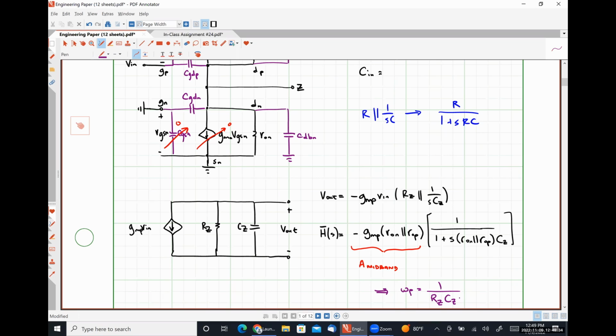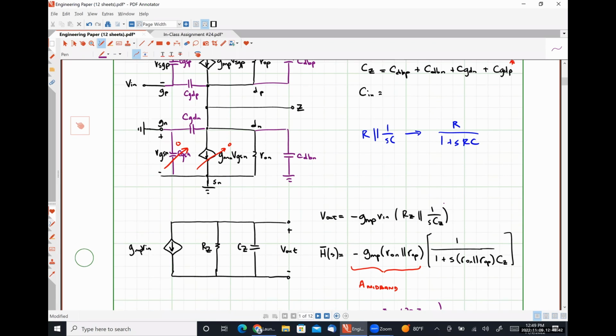All right. So before we move along to bigger and better things, let's talk very briefly about the capacitance that's referred to the input and why this is going to be important. When we looked at the differential stage yesterday, we didn't mention any capacitance referred to the input whatsoever, although we used Miller's theorem to split up multiple feedback capacitors, so there should have been a capacitance associated with each of those input terminals.